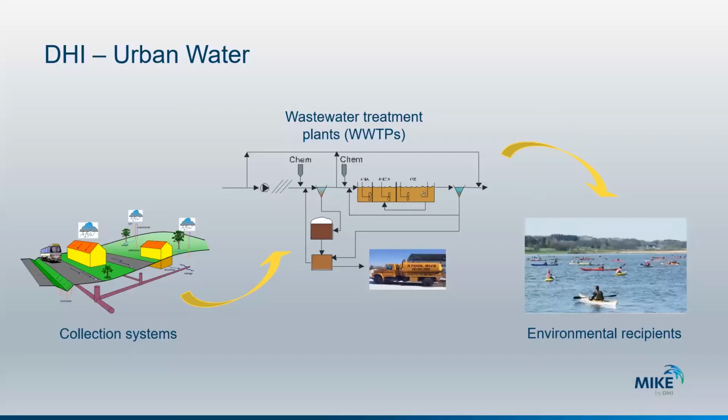Next slide, please. Our Urban Water Department focuses on the full system of water modeling. We were the first to complete a surface water pipe network integration model. The urban hydrology is modeled as it flows over a 2D system. The infiltration and inflow enters the pipe through the cracks, the breaks, the manholes, etc. The infiltration and inflow, along with the daily sewage flow, is then hydraulically routed to the wastewater treatment plant.